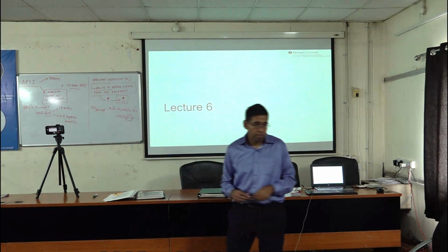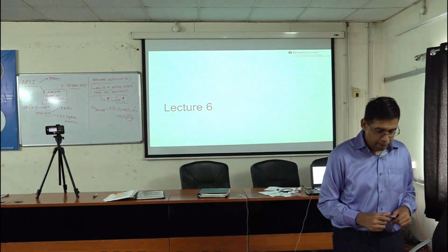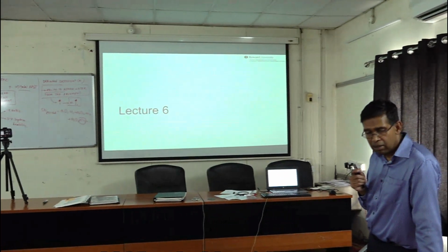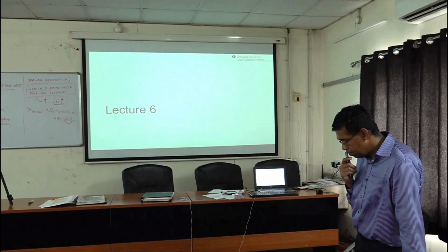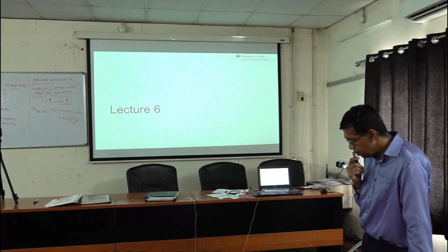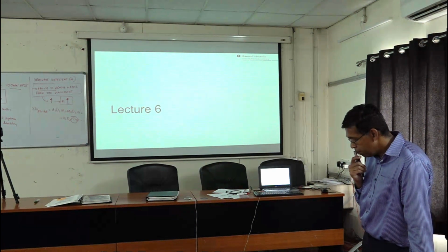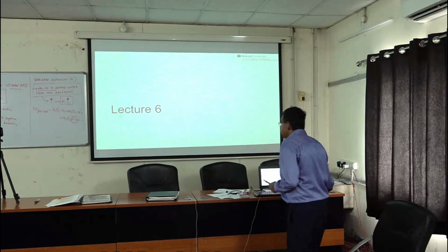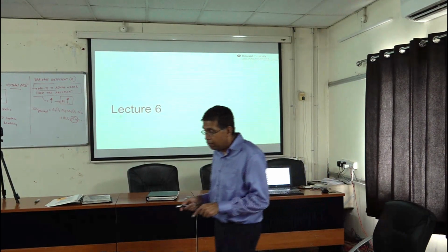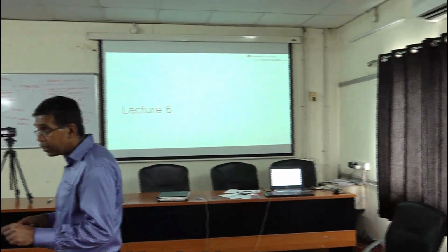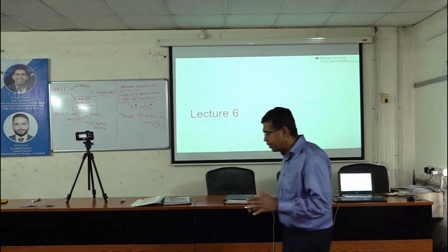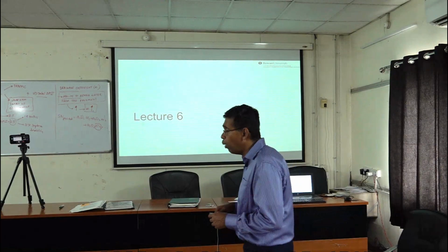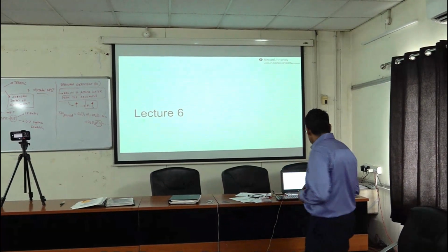Sir, in India we use the effective CBR. The embankment and subgrade have different CBR values. Okay, the effective CBR. So in this method, is there any possibility to find out this effective CBR? There are relationships to correlate CBR to modulus. There is a straight equation. One of the equations is, I think, MR is 1500 times CBR. So somehow you have to correlate CBR to modulus values.